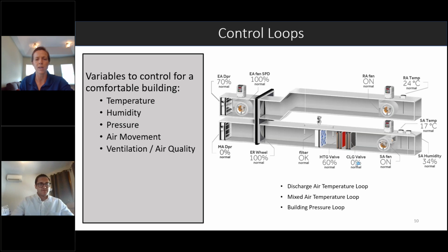Yeah, similarly, and I think you kind of answered the follow-up question we have here, which is, what's the difference between a binary airflow switch and an analog airflow input? Yeah, so the switch is just telling you, is there airflow or isn't there?